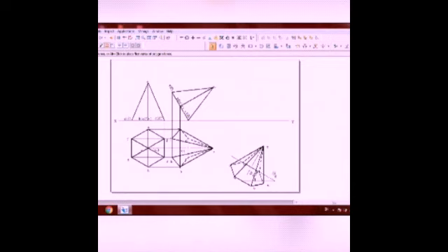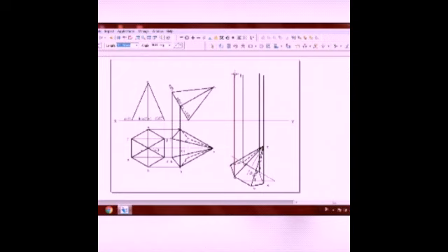Once you align it to the final position, you can draw the projections. That is, from the base you can draw the projection lines, that is, construction lines. Of course, one of the baselines is coinciding with the apex. The remaining lines you draw, starting from the corresponding baselines A, B, C, D, E, F. Since these are construction lines, they will be light lines.